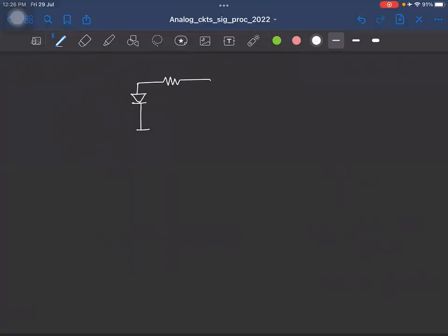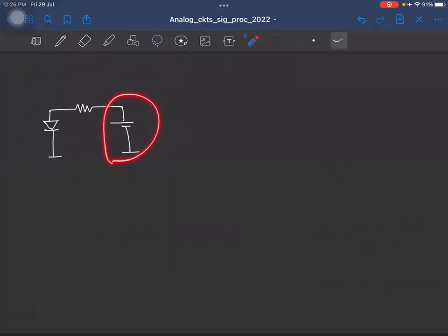No, but the diode is not on, right? It has to be forward biased. Okay, yeah, this is a good suggestion. But again, it looks like we need a voltage source, right? On chip we can get good current sources using MOSFETs. So is there some other suggestion? Even the fact that on the chip you can realize a decent current source.